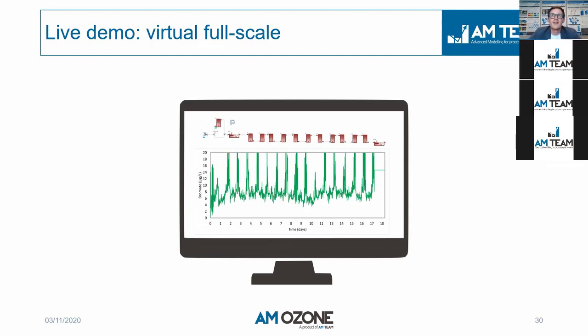Yeah, so the thing is, it's maybe hard to understand. We have limited time to explain all of this in this webinar. But actually, to run this model, we don't need the absolute concentrations of your micropollutants. The model will always give you the relative removals of whatever component you have, even without micropollutant data. Because the micropollutant levels in such matrices have no impact themselves on ozone consumption, for example. We are not talking about industrial wastewater here. We are talking about trace organics.